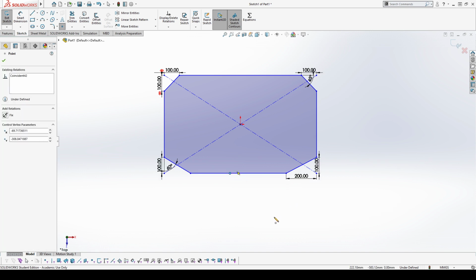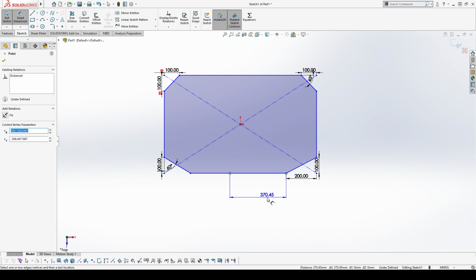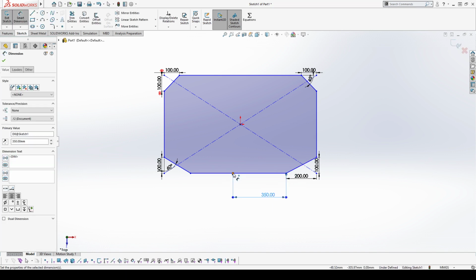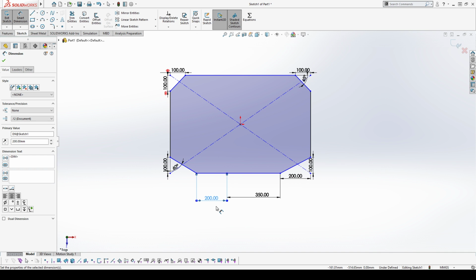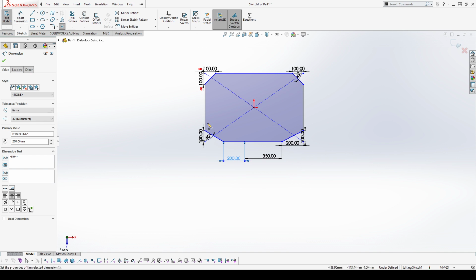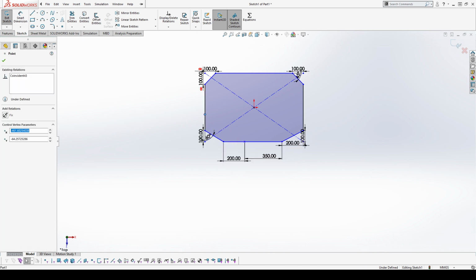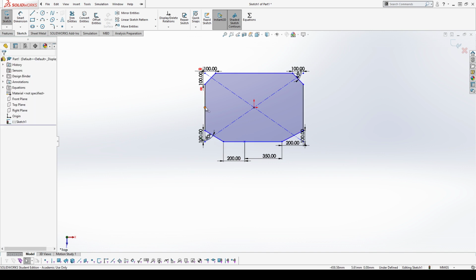So for example, let's say that this is going to connect to something else later on, and I know it's going to need to be like 350 millimeters from that point, and then this point's going to have to be like 200 millimeters, right? And then that way kind of split it up instead of having to do all that math, or if I want to create other geometry off of that later on, it's nice to add in those extra points early on. And then with points before, if I place that point on the line, I want to make sure it's the midpoint of it. I can go in and add in that midpoint relation. So now I have a physical point that's on that line that I can reference that's coincident to that midpoint.